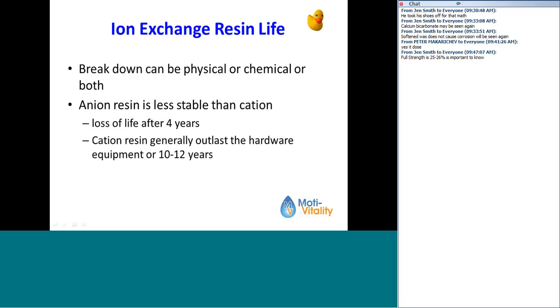Now, I've had people comment when I say 10 to 12 years, well, I've seen water softeners with the same resin and it goes 25, 30 years. That's true. And it doesn't mean that it completely breaks down or loses all of its capacity. It just starts to lose some of its capacity after that 10 to 12 year range. So you are going to have to set that softener up to regenerate more and more often because it is going to begin to break down.